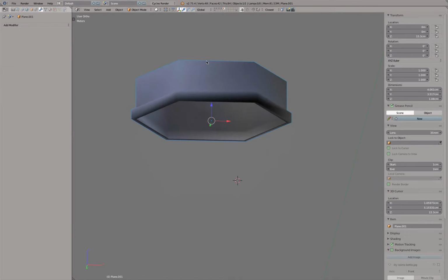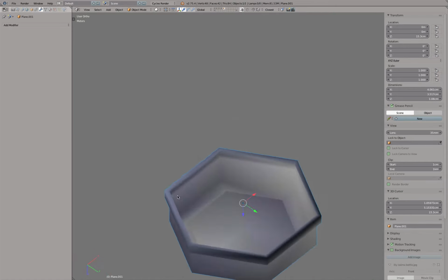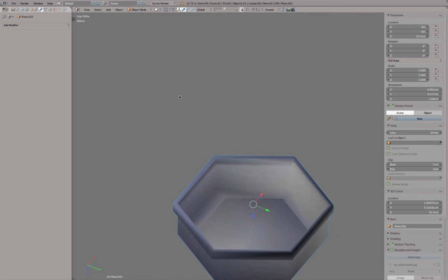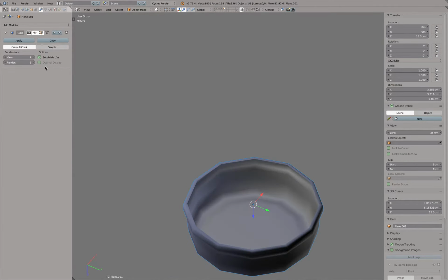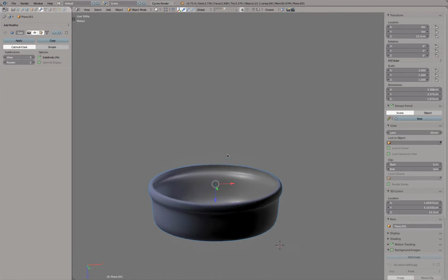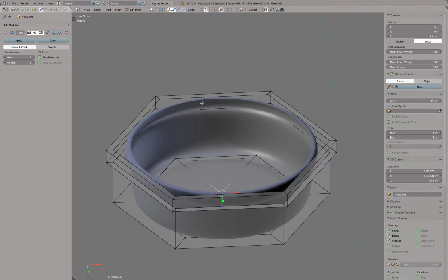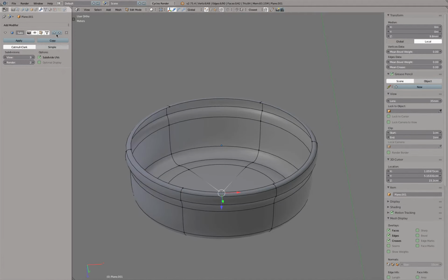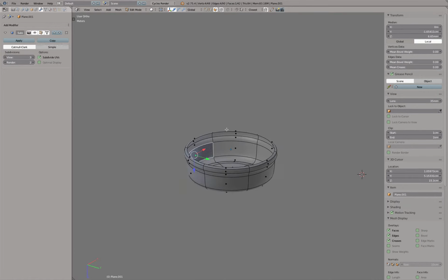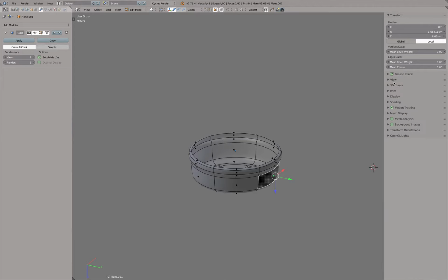You will see that oddly the mesh is kind of bluish and the inside is kind of silver. Specifically, this will be more visible when we add a subsurface. So what does that mean? Let me introduce you to what we call surface normals. So let me go to face select. Maybe I select this face or this face, and then I go to the property panel and I go to mesh display, and there are normals.